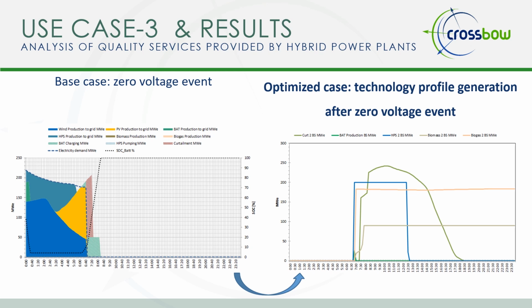It can be observed that the agreed production schedule is terminated once the failure in the system occurs. Next, the battery energy storage system automatically tries to charge with energy production from the photovoltaic and wind plant at maximum charging power until it achieves its maximum capacity. The energy production that a battery energy storage system cannot absorb is called a curtailment. On the other hand, figure right shows the startup curve by each technology and how the hybrid plant could contribute to restore the electric system.